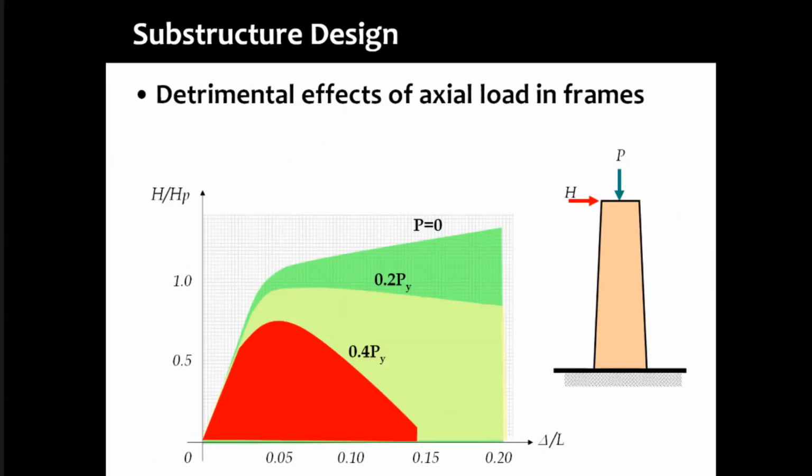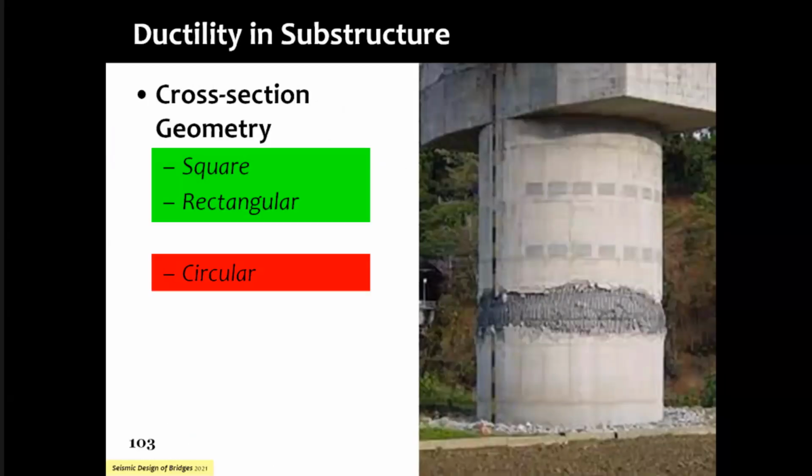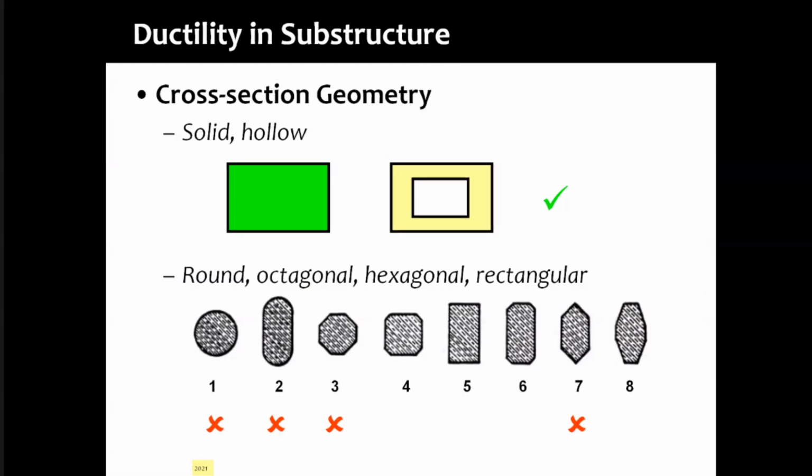right? So axial loads, as I said, are painful for us. You can see this for vertical shaking. There's an elephant foot buckling of the reinforcement between the stirrups, transverse stirrups that are there. So we are looking at the spacing of these stirrups to be much more stringent than what we would do normally. And the other issue that we are seeing is that you have large number of cross sections